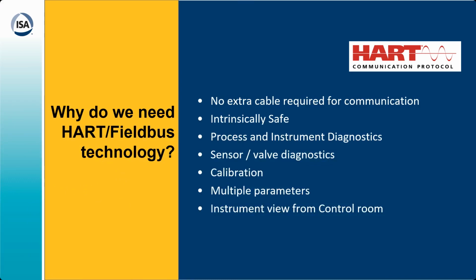But apart from that, you don't need to lay extra cable, because in the process plant so many cables are already laid. Our technology works on the standard 4-20 milliampere loop, on the existing cable which you already laid for getting data to your PLCs.